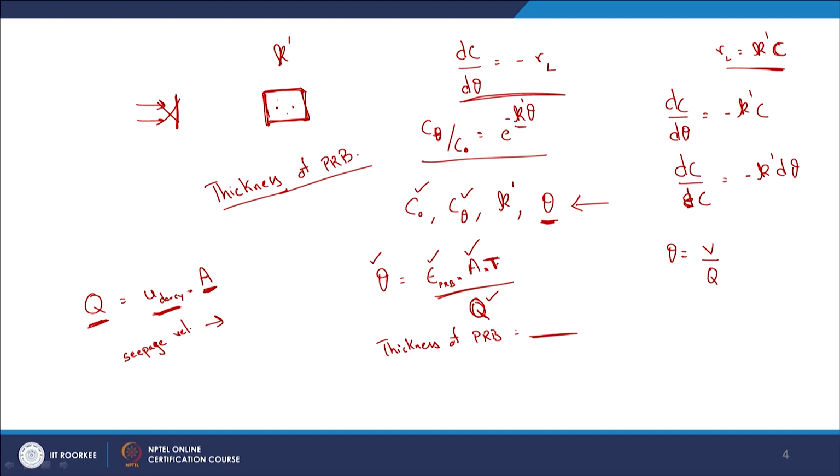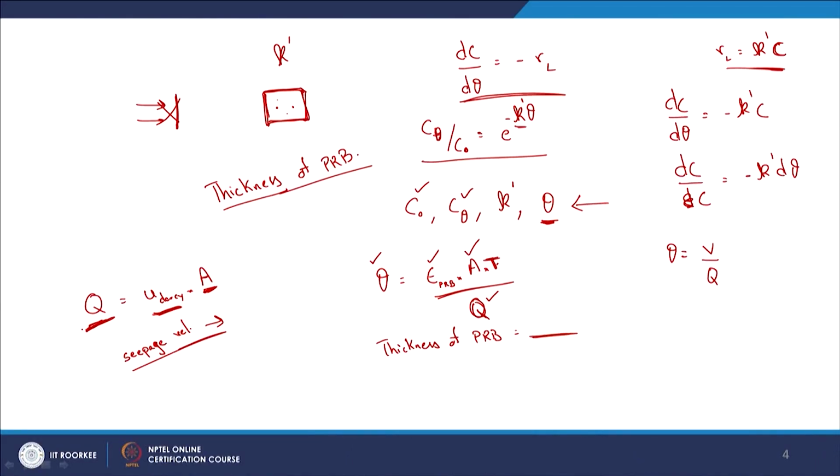But if I do not have the Darcy's velocity, but the seepage velocity, what is seepage velocity about? So, here in groundwater you have soil and then the pores, right. Where is the groundwater flowing through? Through these pores, right. So, the velocity of that particular groundwater through these pores is called the seepage velocity. So, if you obviously think about it, the seepage velocity is going to be higher than the Darcy's velocity, right. So, when you are writing it down or trying to calculate Q, you need to try to understand, do you have the Darcy's velocity or the seepage velocity.